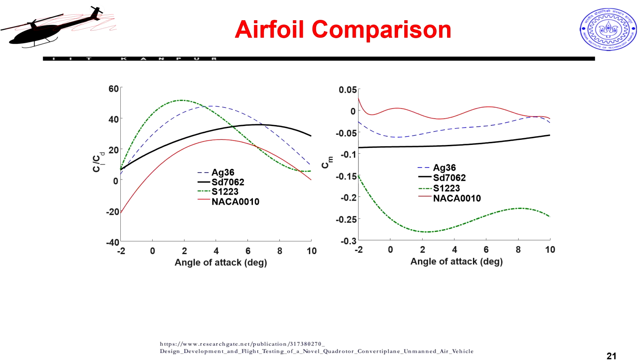That is going to give me a slightly better understanding, and I do that. So, here it is. I now have CL by CD versus angle of attack. This gives me a slightly better picture: look, my L by D is very similar for the blue line and the green line.